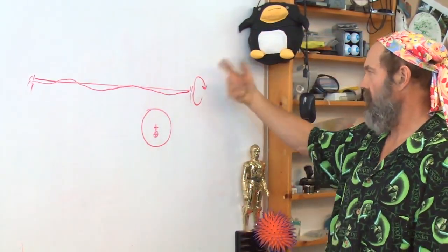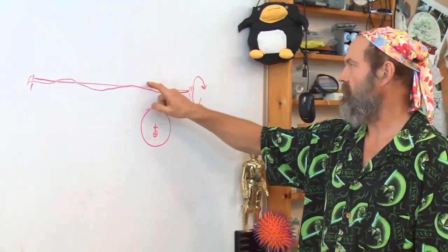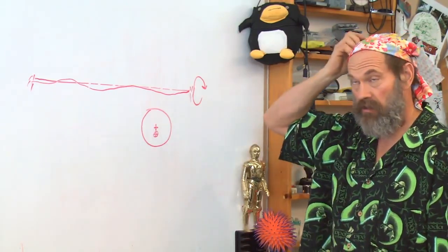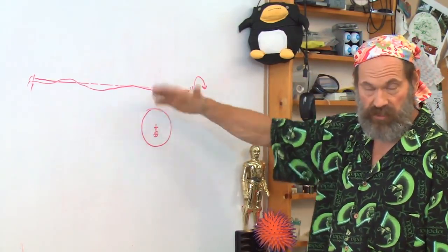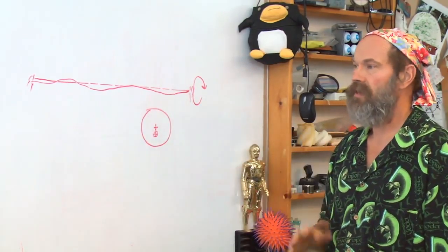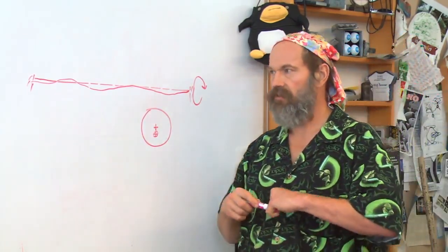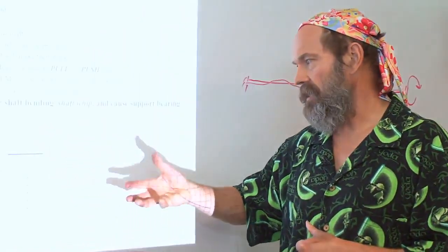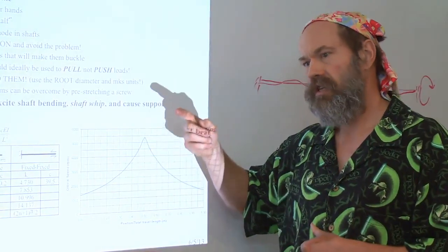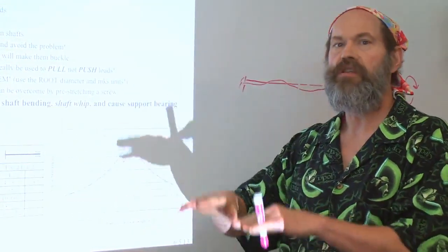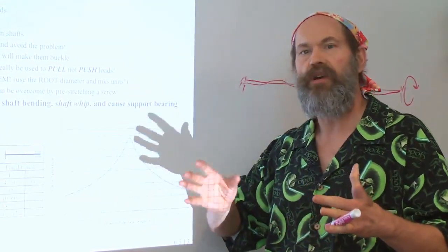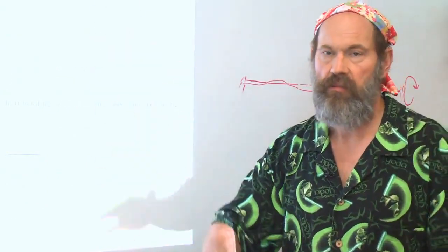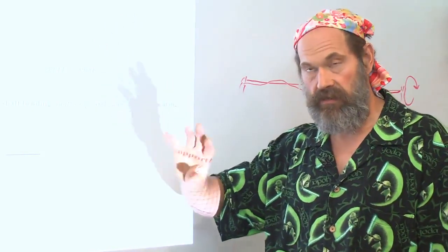That tells me as I rotate about the ideal center, I now have a rotating mass. So it can cause an instability. It's a force that's shaking things, pushing on things sideways. That can excite the natural frequency of the screw shaft. So the rotational speed can excite the bending frequency of the shaft. There's also a torsional vibration mode, but in these types of long shafts, it's really the sideways bending mode that's excited by the rotary speed.